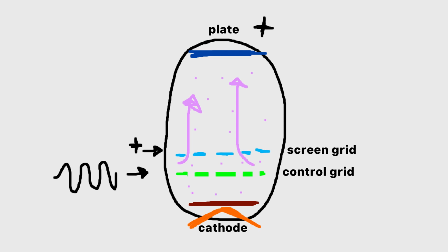And this design works well, really well in fact, too well. Boosting these electrons causes them to move so fast now sometimes that they hit the plate so hard and bounce back off of it. And some bounce so hard, they end up being more attracted to the screen than the plate. And this causes a unique disruption to the load where it alters the operating conditions and by effect the transfer curve of the tube dynamically. But it still gives us greater precision, which can give us a greater range of power.